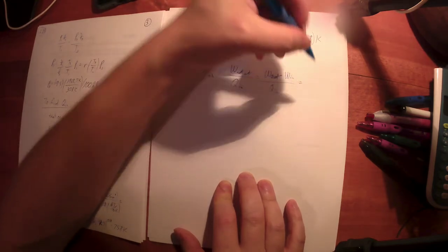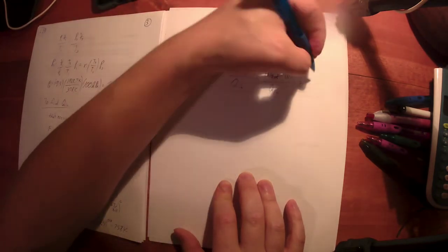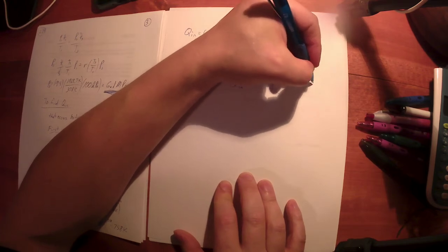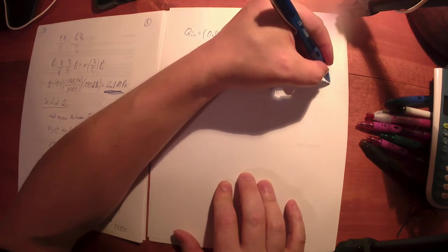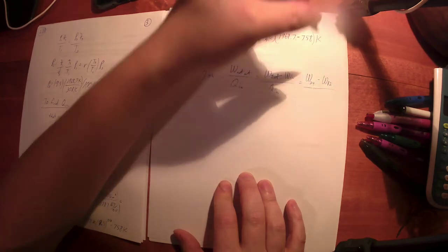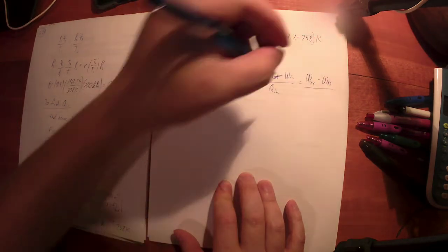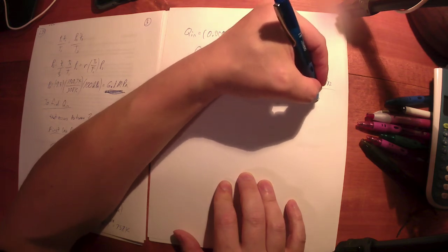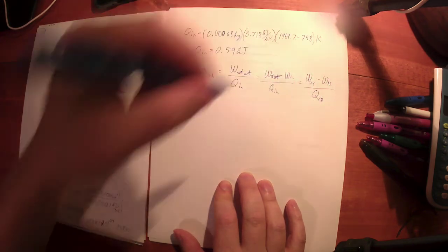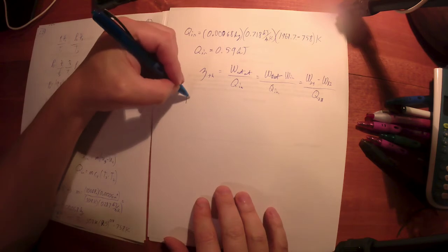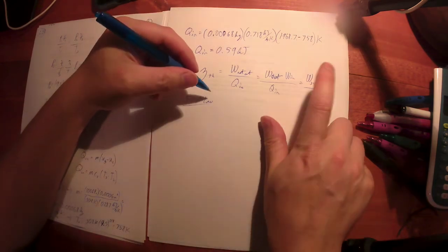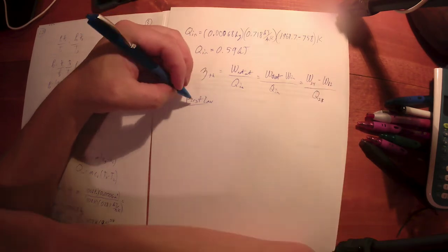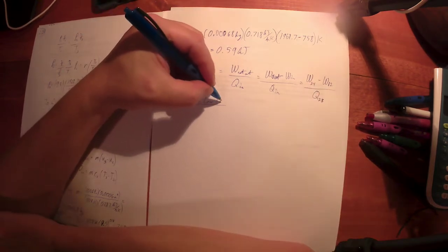Well, where does this occur? Well, the work out occurs during the expansion process. That's from 3 to 4. And the work in occurs during the compression process. We could go back to the diagram and see that. That occurs between states 1 and 2. And the heat occurs between states 2 and 3. Now, if you set up your first law, right, how do we find these works? Well, an unknown energy could be found through the first law.